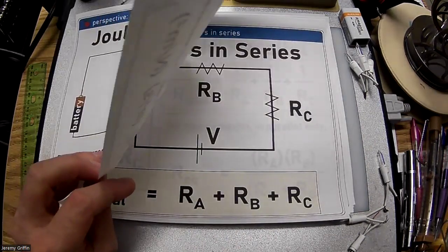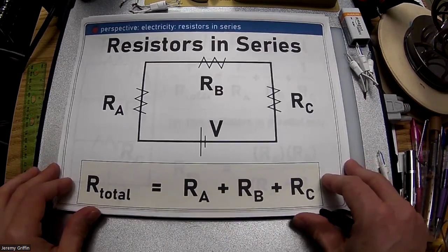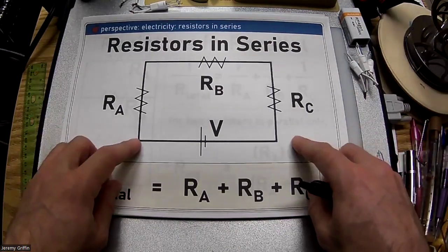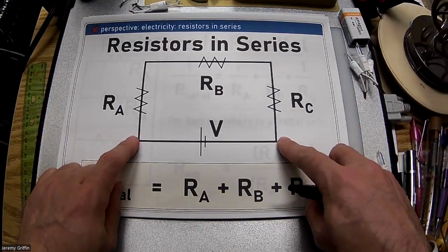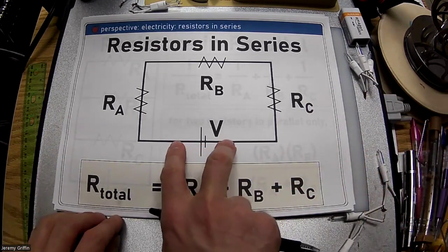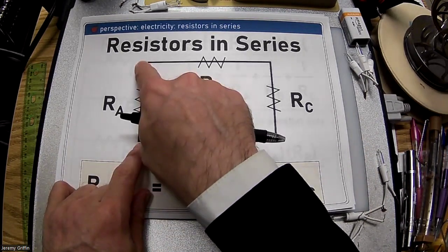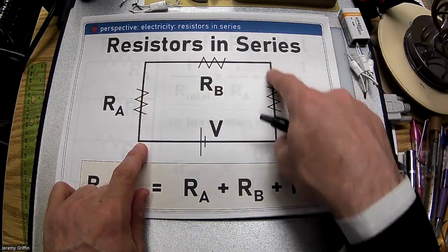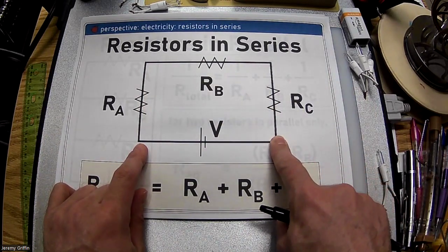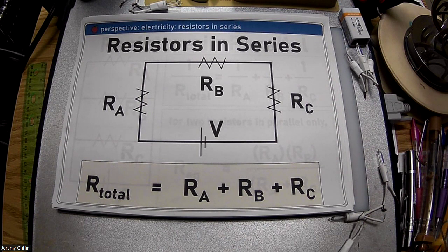All right, let's start hooking up these resistors different ways. And we'll start with real simple. The simplest thing I could do is just in series, just one after another. And this I already showed you guys earlier today. So here's my battery right here, or my potential difference, my 2 leads, right? And then go through 1 resistor and the 2nd resistor and 3rd resistor sequentially. See how the current has to go through all 3 resistors, one after another sequentially, right?